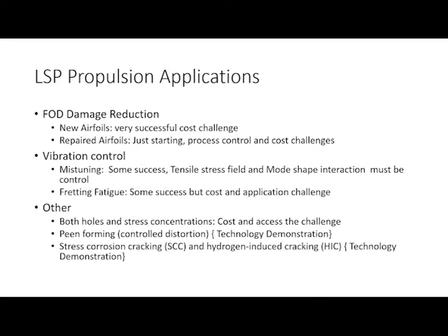The one thing we do know is that you've got to really manage the tensile stress field that you generate and the mode shape, because there will be an interaction, and you don't want that large tensile stress to occur where your mode has a high strain to it. I do know of one engine application where it's been successfully used on fretting fatigue.